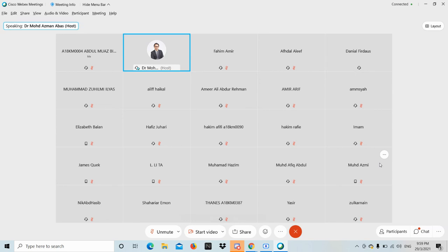So the only way for you to observe is to look at your engine temperatures and whether there's any rough noise. Those are some of the indications saying that no, RON 95 is not good, please go back to RON 97. So what we did was drain back the RON 95 and fill up RON 97 again. But there's a risk during the tryout that it might damage your engine. If you're willing to take that risk and try out the car discreetly, then it should be no problem.